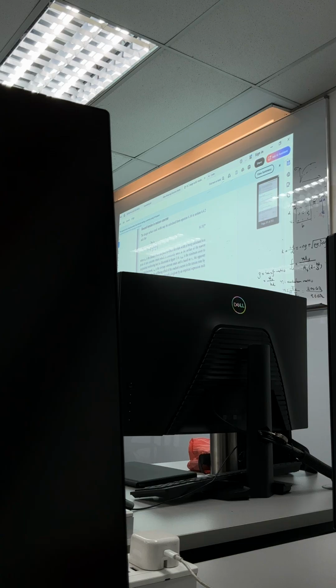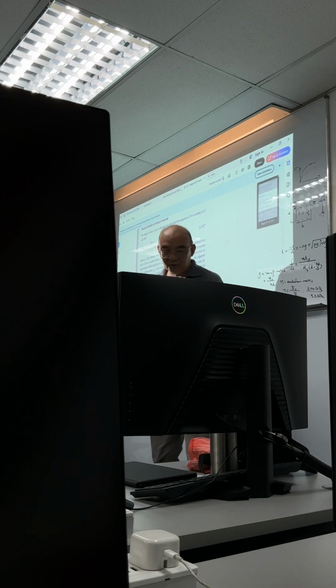Okay, and then here it says a_cr is the distance from the point at which the crack width is being calculated to a point of zero compressive strain. So what is a_cr? So we say taken as the surface of the nearest bar as illustrated in 11.6.